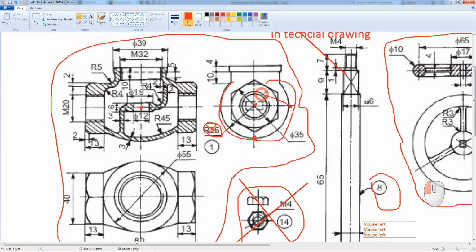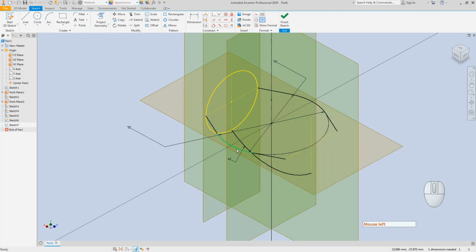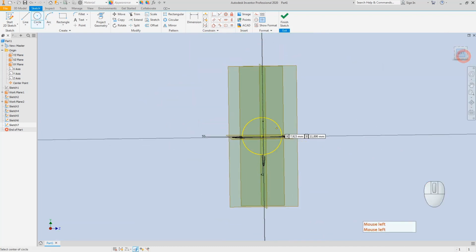As told before, our dimension is not suitable for this arc shape because it must be 55, and this 55 millimeter radius pathway does not fit this dimension. For this reason, I would like to just make a relationship between our paths and our circle. We will create a relationship by using these pathways, projection, and lines.